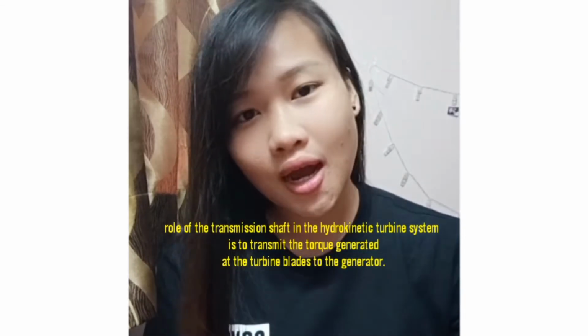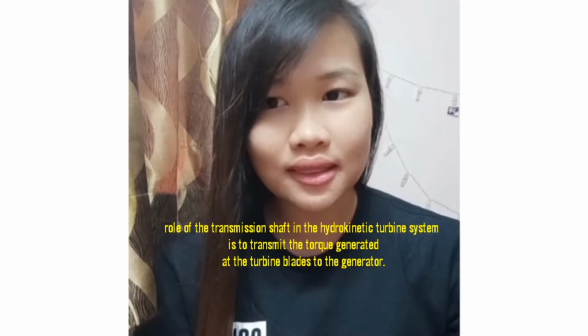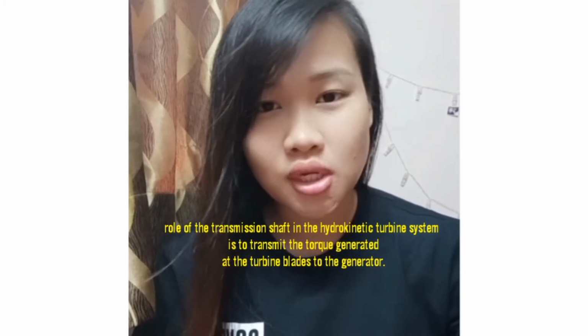So we move to the transmission shaft in hydrokinetic turbines. The transmission shaft is the first component to receive the power generated at the turbine. The role of the transmission shaft in the hydrokinetic turbine is to transmit the torque generated at the turbine blade to the generator. This is done using mechanical power transmission components such as chains, gears, sprockets, belts and pulleys, and keys.